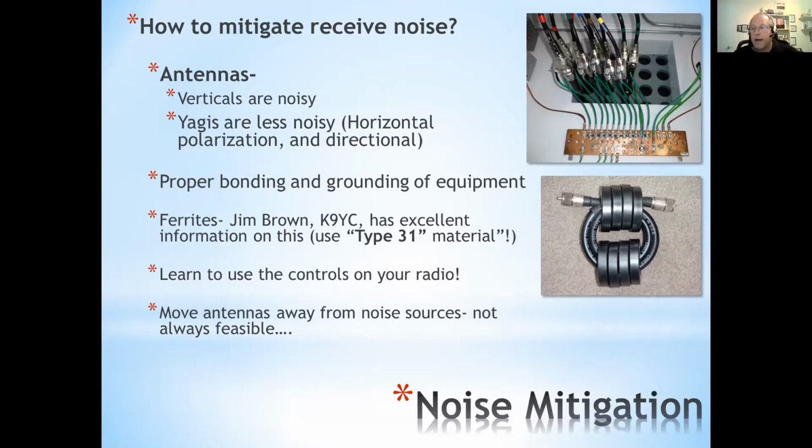So there are times where I can try to pick up a signal, for example, on 20 meters, and there'll be about an S unit and a half, or sometimes 2 S units of difference in noise level between the very similar antennas. They're both 3-element Yagis. I've got a 3-element stepper at the main one and a 3-element tri-bander on the other tower. And you can be aimed at the same signal. They'll both be the same S units, but the background noise level will be about an S unit and a half higher on the one that's closer to my house. So if you can, try to move the antennas away from the noise, but unfortunately not everybody's lucky like I am and has a couple of acres that can spread things out. I just happen to be very lucky.